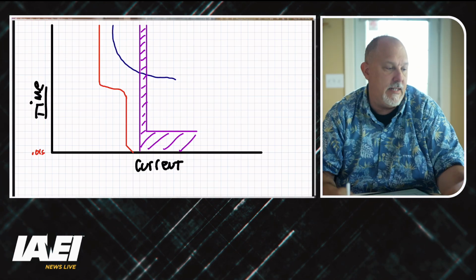If you think about our ampacity discussion, we said that if you have a conductor and a continuous load or a non-continuous load, you would pick a conductor size and an overcurrent protective device so that the overload, the circuit breaker or fuse ampere rating, is less than or equal to the 75 degree C column if it's 75 degree C equipment. You can't go to the next larger. Well, they do the same thing on motors.